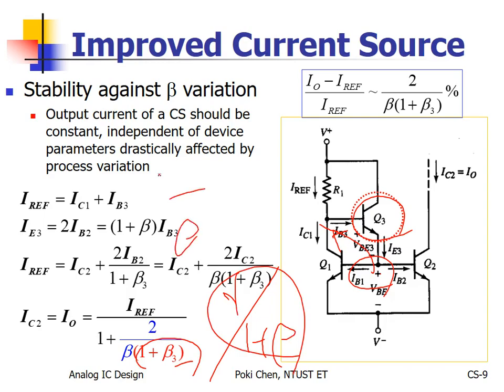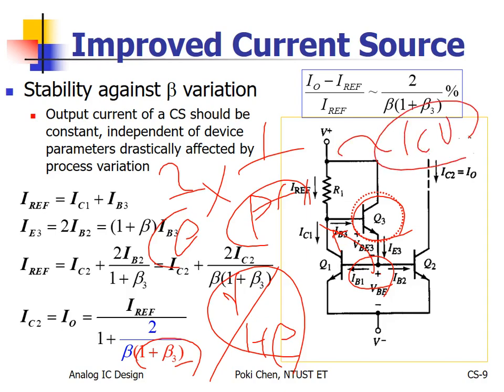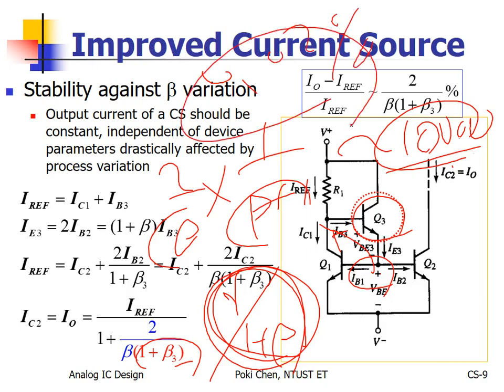Okay, so from the beginning it is beta 2, and right now, congratulations. So how much is beta? Usually for BJT, around 100, but with a lot of variation and mismatch. Later I will explain a little bit about such kind of mismatch. Anyway, in the past, you can guess the magnitude of mismatch is around 2%. But with the help of the other term, for attenuation, right now it becomes almost 0.2%. Bingo. From 2% to 0.02%. Very, very good.